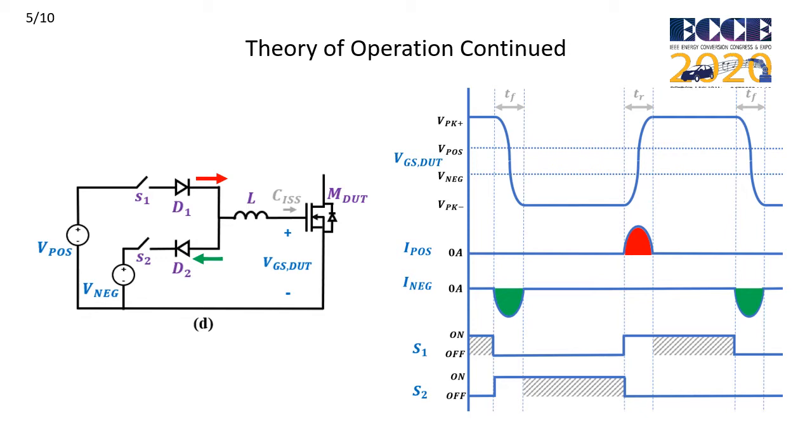As mentioned, D1 and D2 relax the turn-off timing constraints on S1 and S2, and that's indicated here by the shaded or hatched regions. The switches can turn off at any point during the shaded region without affecting the gate driver's performance. So since the gate swing is entirely dependent on parasitics, we really need to pay attention to which devices we use.